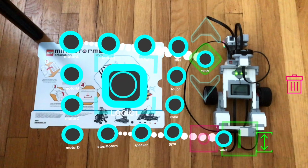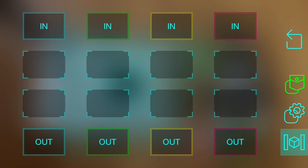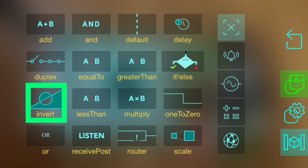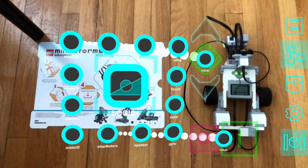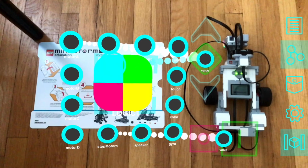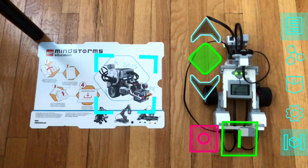Next, we're going to drag in a logic node. If you haven't seen our video on this, you should go check it out. We're going to open up this logic node, and from the pocket, we're going to grab the invert tool. So this is going to allow us to multiply any number by -1. So let's connect it to the blue input and the blue output. And then if we go back into our programming tab, we'll connect the slider up to the blue input, and then from the logic node, the blue output is going to go to the motor D. So this will run motor D in the reverse direction of motor A.